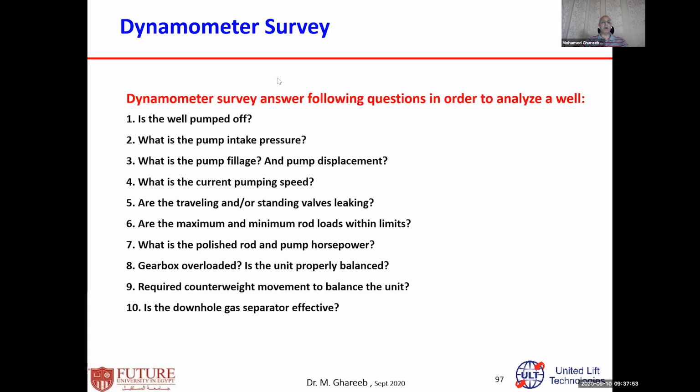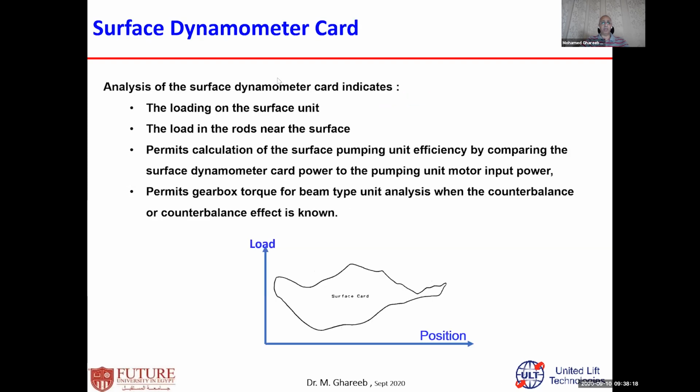What is the pump fillage, and what is the pump displacement, how much the pump is producing, and so on. What's the current pumping speed, which you can measure from the surface; it's not important to be downhole. Is the traveling and standing valve condition working okay, leaking, stuck, closed, or open, and so on. What's the maximum and minimum pump loads, and so on. All this can be analyzed while I am testing the pump.